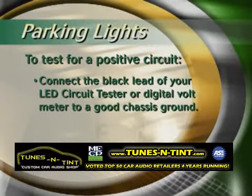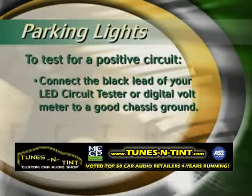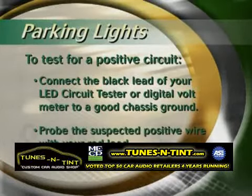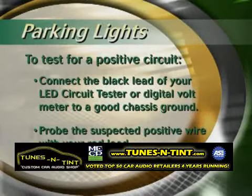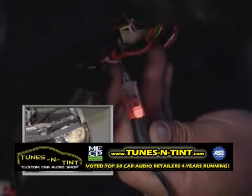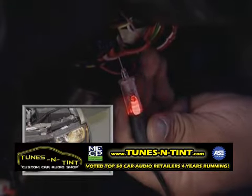When testing for a positive circuit, you will need to connect the black lead of your LED circuit tester or digital voltmeter to good chassis ground. Probe the suspected positive parking light wire with your red lead. When the parking lights are turned on, the red LED on your circuit tester should light. When the parking lights are turned off, the red LED should turn off.